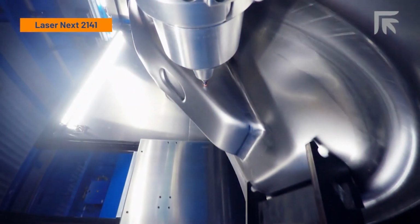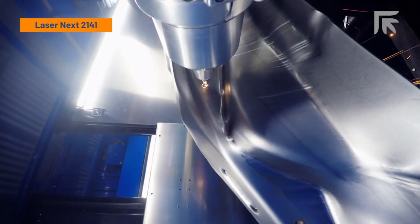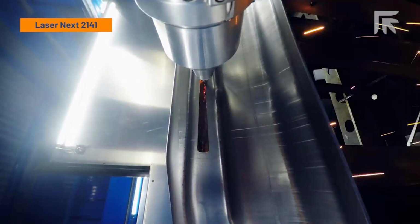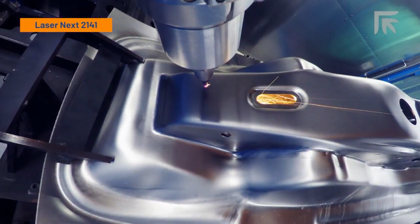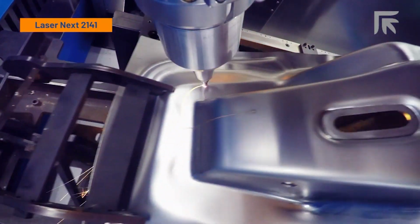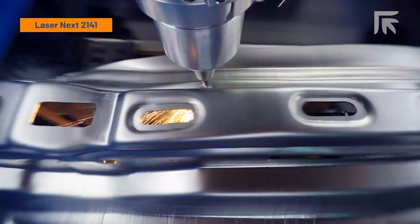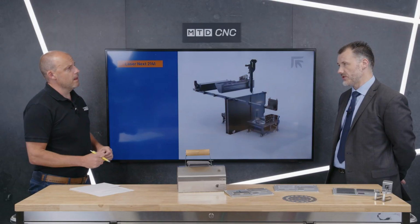The line between CO2 and fibre has become quite greyed, I think, over the last few years as fibre technologies really come on stream. CO2 applications generally tend to be now more with thicker materials, with less laser specific type materials, whereas with fibre you would generally use a more laser grade type material, higher quality. And also with thicker materials, CO2 can be that little bit better in terms of the speed that you would actually get cutting thicker materials. It's not quite so sensitive to the cutting conditions as well.